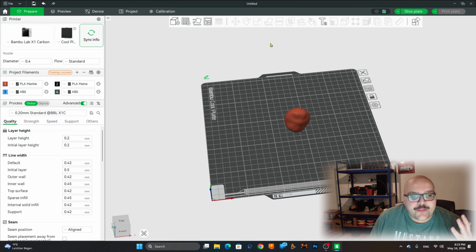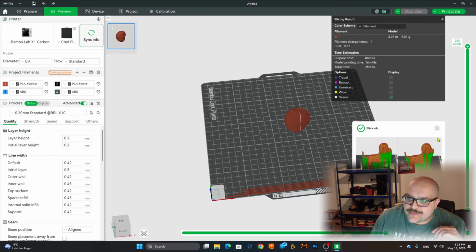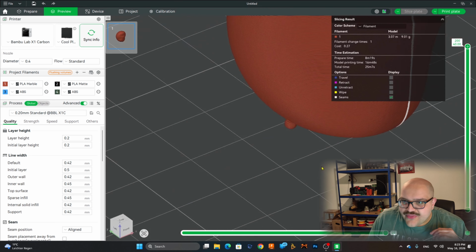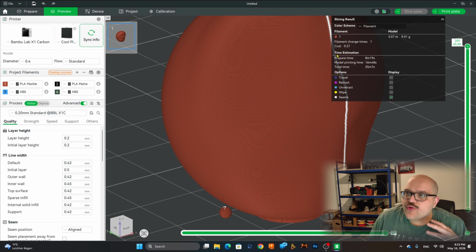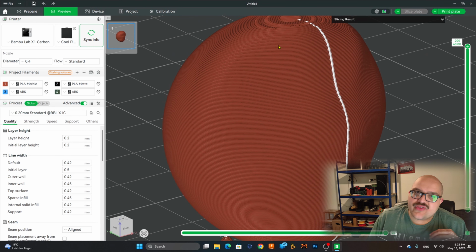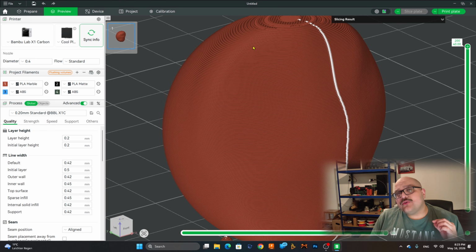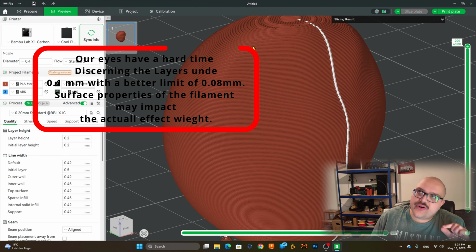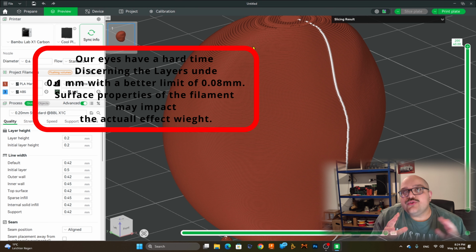As you go to lower and lower layer heights, you start to almost have an injection molded feel, like the outside surface is almost perfectly fine and continuous, so you do not see the layers interrupting. As a matter of fact, if I slice here, you can already see this is what we see even in an actual print. You see those lines. Now those lines become less and less visible as the layer line gets smaller and smaller, because our eyes start to not be able to distinguish between two points right around 0.10 millimeters.